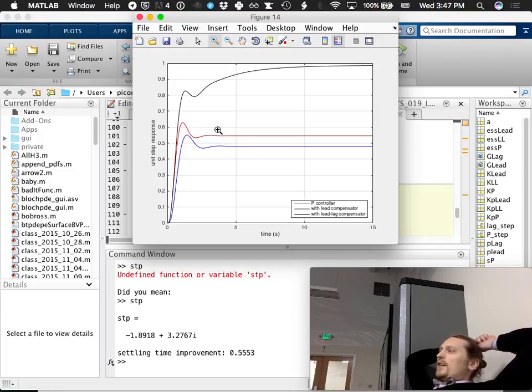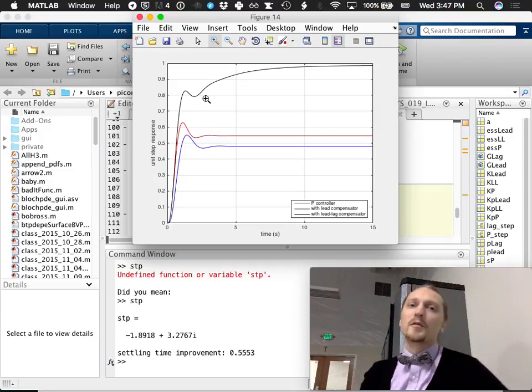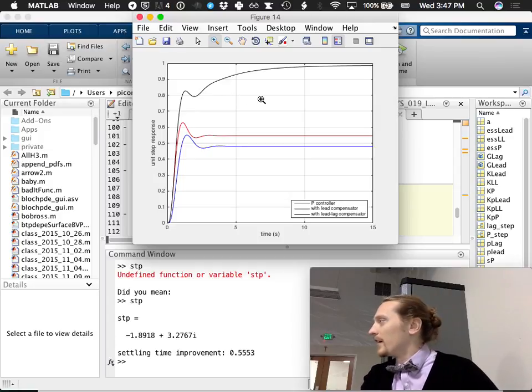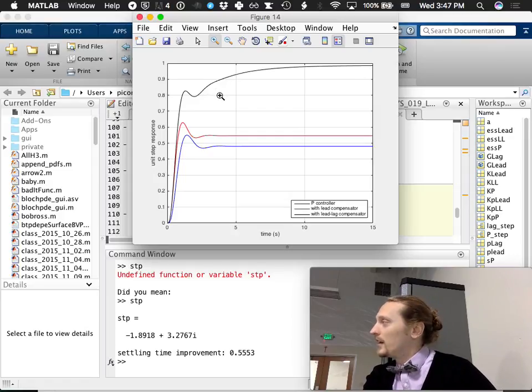It's a little tough. It essentially comes down to this: if you didn't have that steady state error improvement, this thing would have settled out to be about 0.81 or something, right? And in that sense, it settles down to about that pretty quickly, and then it slowly oozes up to the steady state value. So it's not very precisely defined.